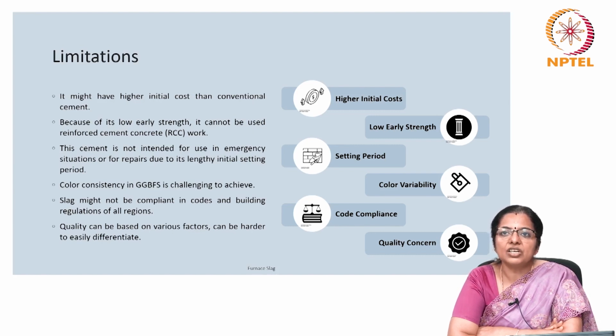The lengthy initial setting period makes it less ideal for emergency repairs. Achieving color consistency in ground granulated blast furnace slag can be challenging because this will influence the aesthetic preferences.